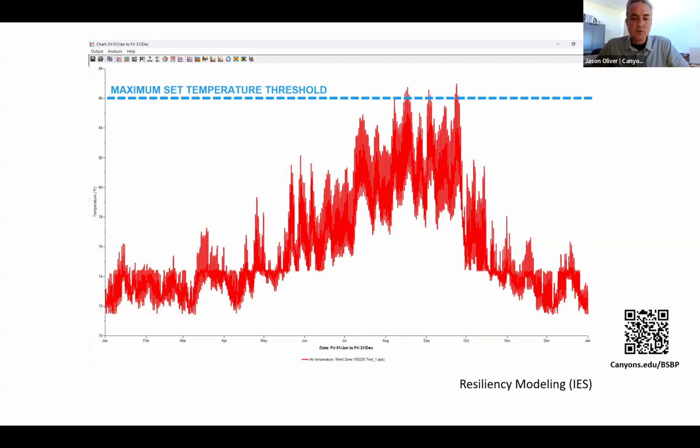And so this diagram, which shows air temperature inside a room annually, we can see in the peak periods that, although there might be a few days where we actually get above the threshold, that at least helps us to isolate, okay, on those days, maybe we need to shield a little bit better against the sun that we might experience in late August or September, or reduce the fenestration that would be in the direct solar radiation beam.